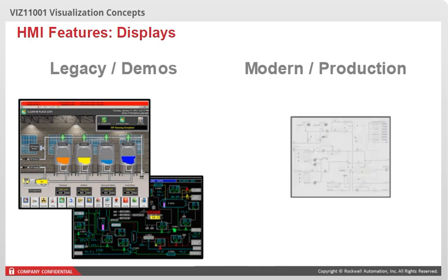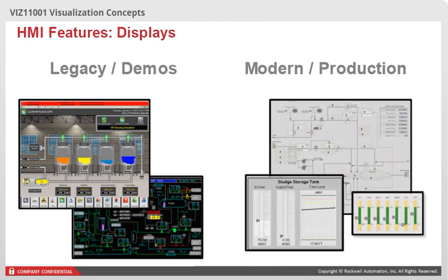With the help of today's standards like ISA 101 and ASM, operators are more likely to be presented with much simpler graphics with grayscale colors. Graphics designed for simplicity and situational awareness ensure abnormal situations can be addressed properly. When an event occurs where operator attention is required, the graphic would highlight that change and drive operator attention to it. Studies suggest that response time to abnormal conditions can be reduced by an estimated 10% with the implementation of a standard user environment designed to ISA 101.